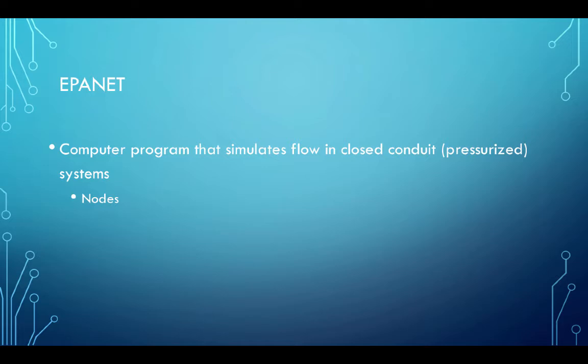At nodes, we're going to specify elevations and demands, and the computer program, once it's assembled, calculates the resulting pressures. In links, those are things like pipes, pumps, and valves, so we specify their behavior, frictional loss terms, settings, and whatnot.